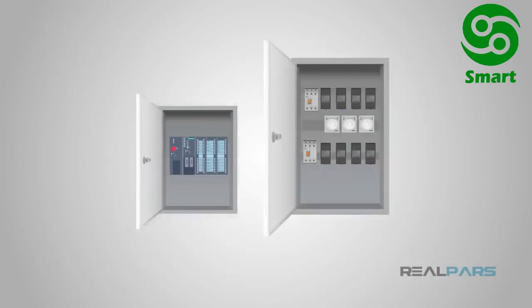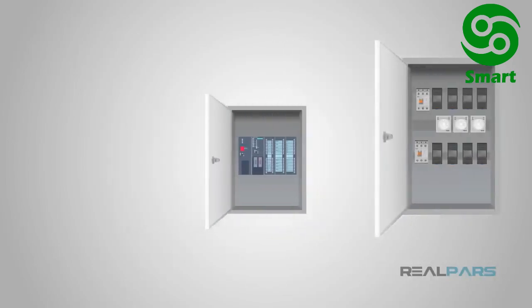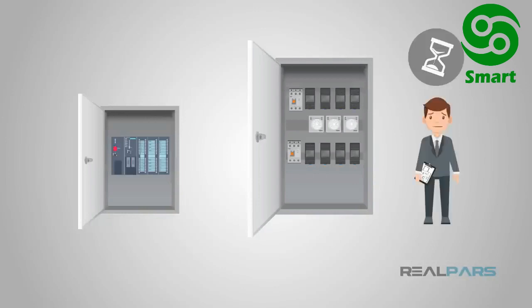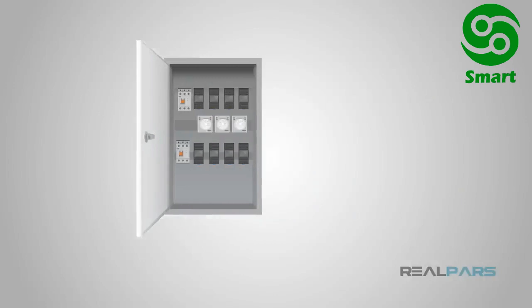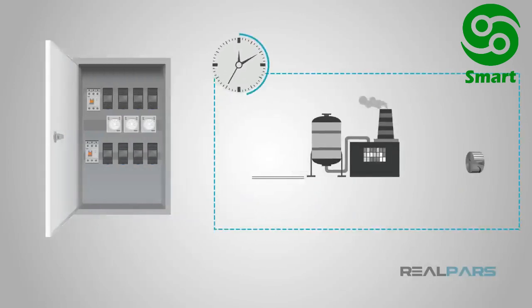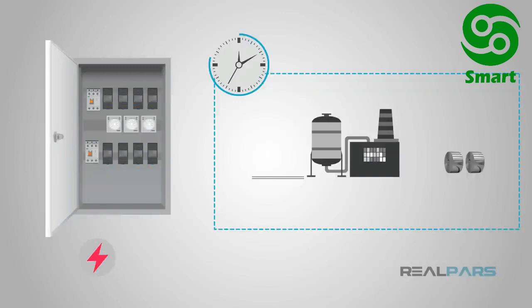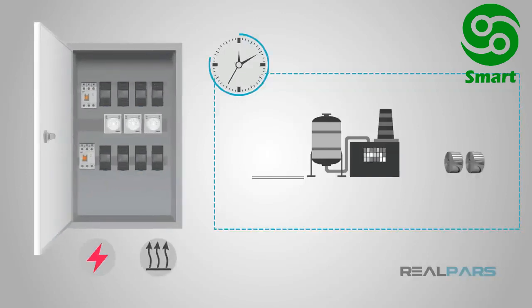Initially, the PLC was a replacement for panels of relays, devices that turn on and off. Making a machine run using relays as logic was time-consuming and challenging, and making a change in the logic or the operation of the machine was almost as complicated as starting over. Relays also fail far more frequently than computer components, so that relay logic required more downtime to keep it running than newer PLC-based controls. On top of all of that, relays use a lot of electricity, make lots of heat and soot, and take up lots of space.